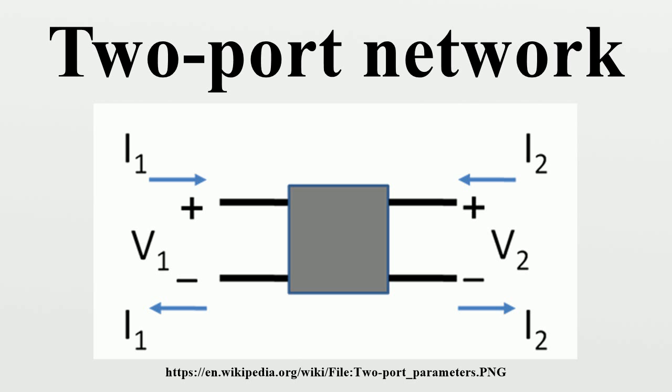Example: common base amplifier. Note: tabulated formulas in Table 2 make the H-equivalent circuit of the transistor from Figure 6 agree with its small-signal low-frequency hybrid pi model. In Figure 7, notation: R pi equals base resistance of transistor, Rho equals output resistance, and GM equals transconductance. The negative sign for H21 reflects the convention that I1, I2 are positive when directed into the two-port.